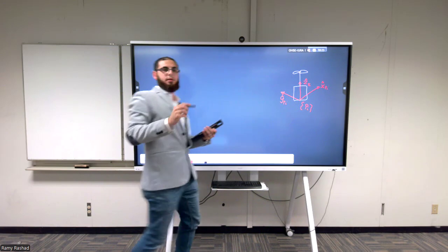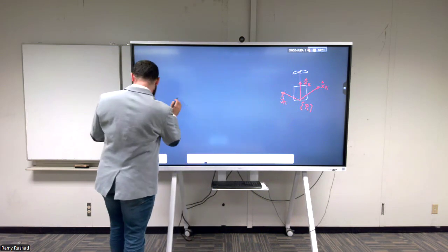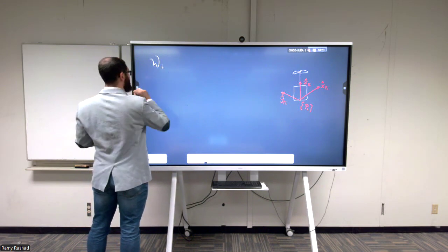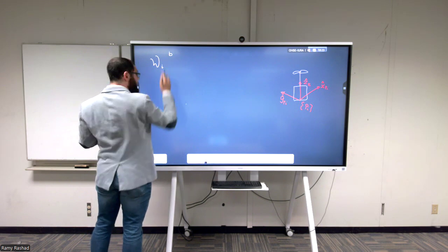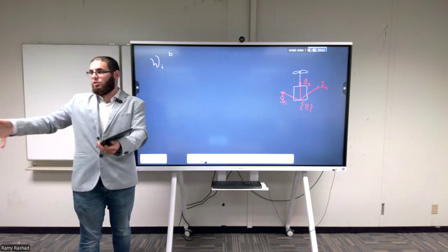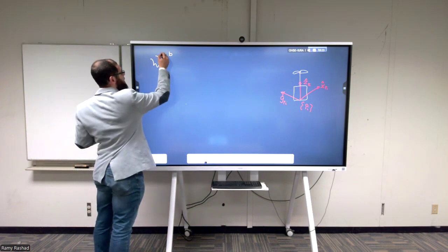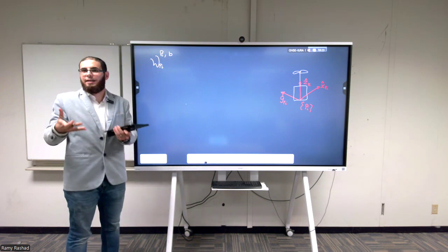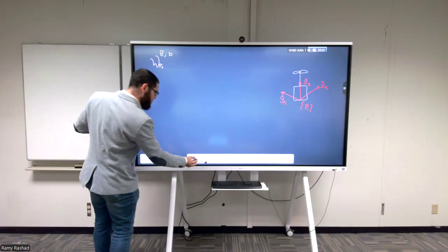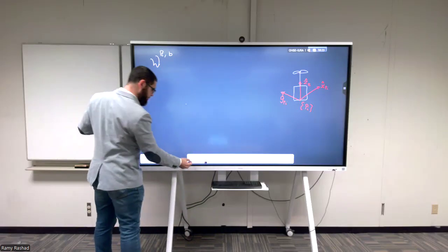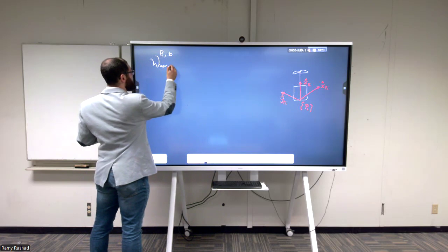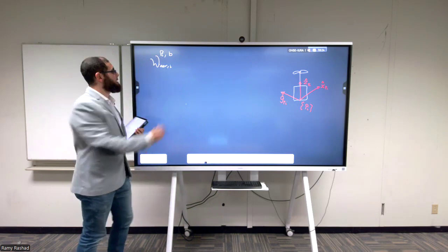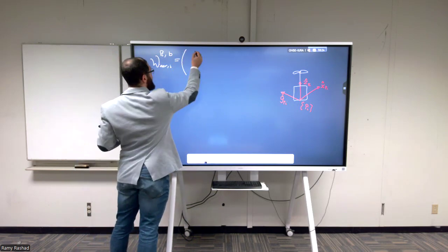is given only by 2 numbers. It has the following structure. It has the wrench applied by the ith propeller, and it's applied on the body that's attached to the B frame, which is the drone itself, the drone structure, and expressed in the PI frame. Okay, so this is the PI propeller, or the wrench, like the aerodynamic wrench. Okay, let's maybe write it like that. So this is the aerodynamic wrench that comes from the ith propeller applied on the body attached to the B frame, expressed in the PI frame, is simply 3 torques and 3 forces.